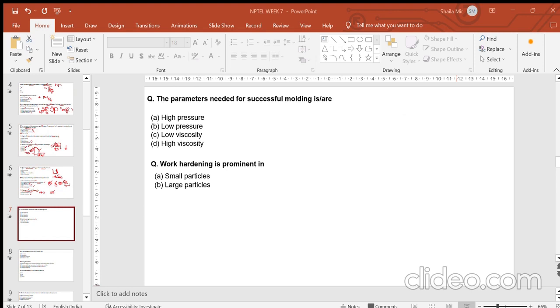Another factor is that the ball mill does not operate at its critical speed. It always operates at less than the critical speed. Say for example, if I write this as the operational speed, it will always be less than the critical speed. Some run it at 60%, 70%, or say 30% of capacity. So you can say that it is always less than the critical speed of the ball mill when you are operating a mill.